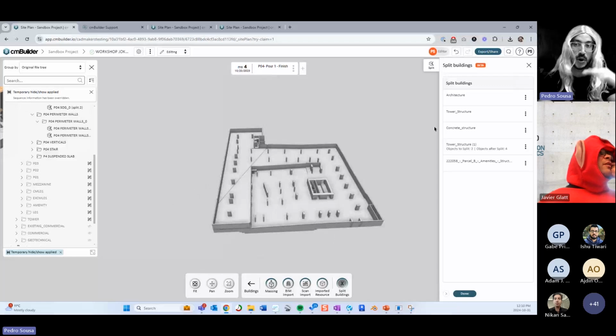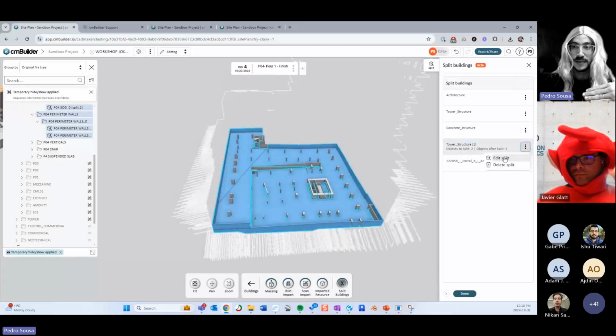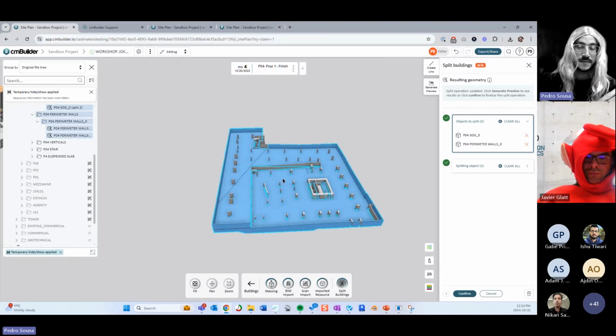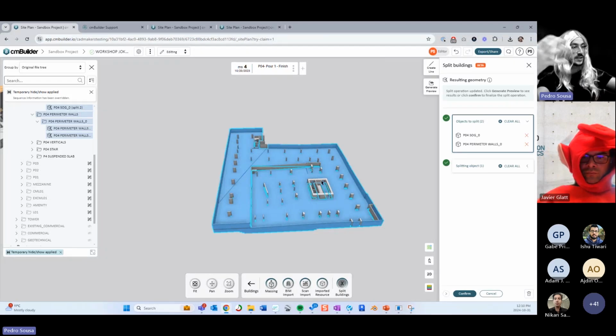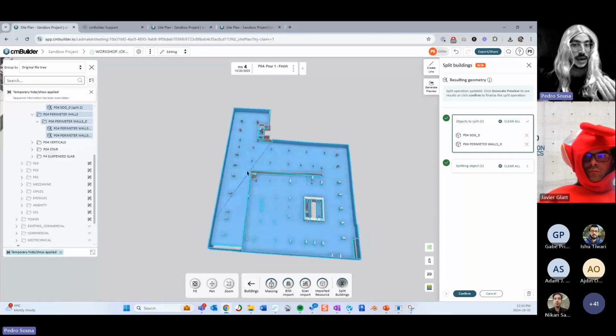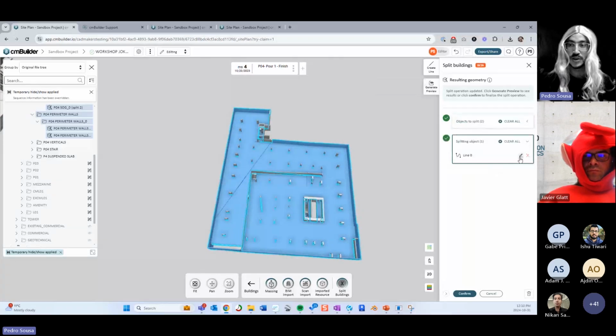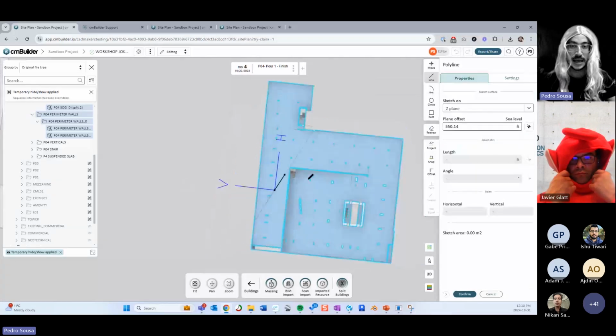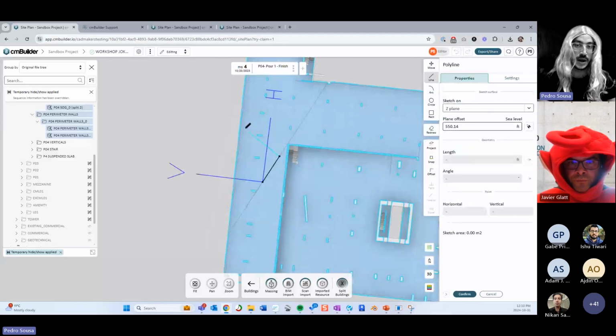And then for the parts that you select on the split, let's say this slab over here, we create a bounding box to understand what the limits of that geometry are. And then we take the slicing element and we slice all the way through it, right? So there is a way for us to interrupt this line so it does not go all the way to the end. Basically, we just need to make sure that with this line, we create kind of a curve, like an L shape like this.